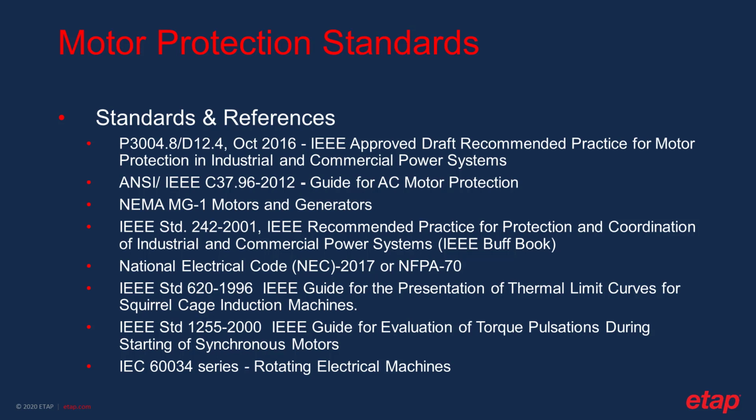All of these standards need to be reviewed and used as the reference for the motor protection depending on which part of your world you are and who's the jurisdiction having authority for the installed equipment. So this standard needs to be reviewed, needs to be known, and the settings set based on this standard unless you have a justification not to follow.